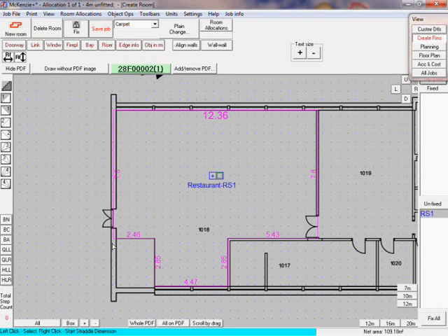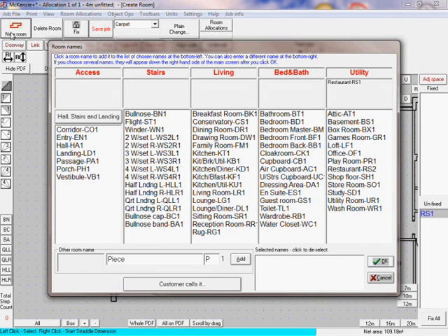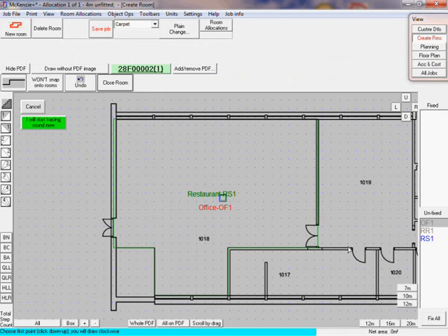We will now create a second room which is adjacent to the first. Click on the Name Rooms button and this time select to have two new rooms, a reception room and an office. When we have clicked OK, the short codes for the undrawn new rooms show in the rooms list shown here, and we can select which one we wish to draw first. Previously drawn rooms show in green outline, so that we can see what has been done and what is yet to be done.